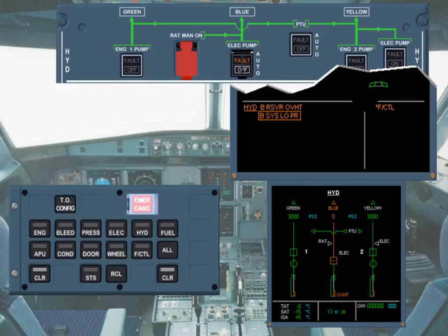Depending on the importance of the primary failure, secondary failure messages can be displayed before or after the primary boxed failure message. If the primary failure affects systems without secondary failure message, the affected system title will be shown with a star in place of the right memos. In this example, flight control system page is affected by the primary failure.